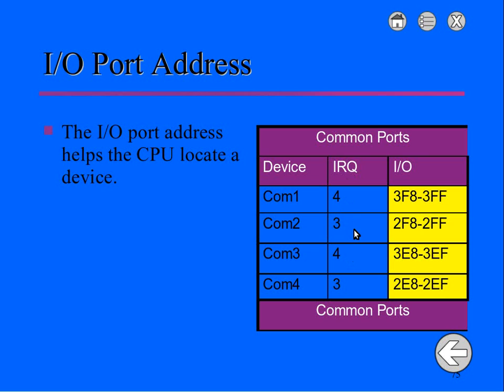That's not really a problem, because what happens is the PC CPU, when it gets an interrupt, knows that, okay, I've got an interrupt from COM4, I just need to identify who created the interrupt, and it can do that by accessing the I/O addresses, and inside those I/O addresses there will be some bit that will be turned on or something to tell it which one of those devices caused the interrupt, and then it will proceed to process that particular interrupt and service that device.